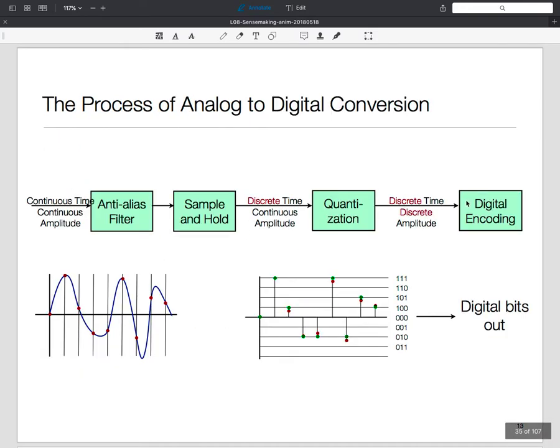So the thresholds I'm referring to are these different threshold voltages. We'll compare it against each one of these conceptually, and then say, aha, it lies in this bin, and therefore the code is 101. Now, to do that comparison, much like you would do comparison in real life, you can either do it sequentially, so check it one by one again, or you can do it in parallel, or some other ways of doing that comparison.